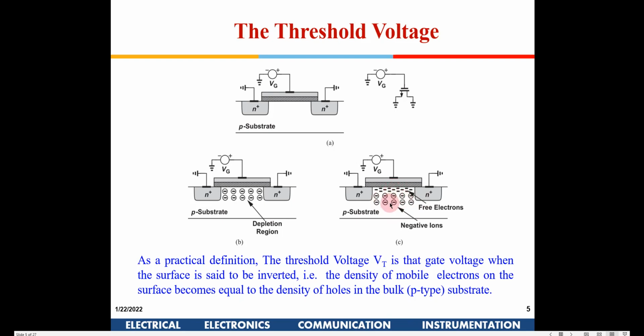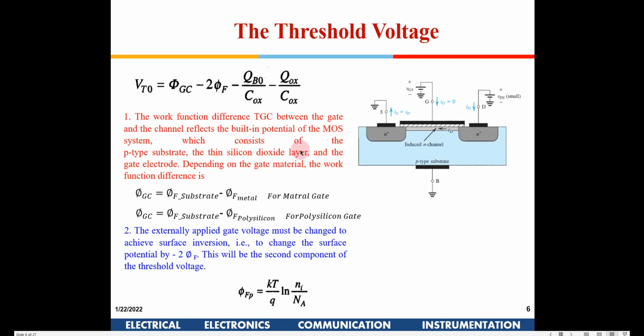Even for a diode you require some positive voltage, right? So an inbuilt positive voltage is required to switch on a diode. Here the diode is in the reverse direction. Here you have N, depletion, then P. So you need to give that extra voltage again, so that this also adds up. This is negative because that electron density will be taken out here. Just understand, in this course we are not going to derive each of them.